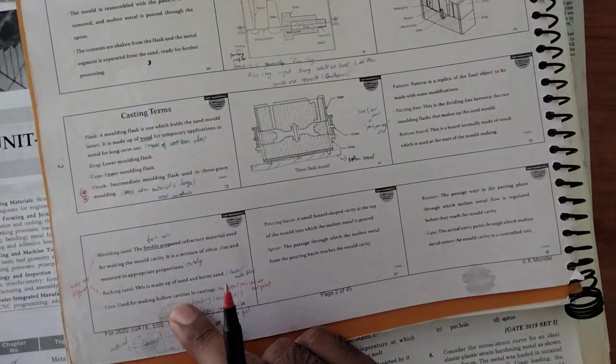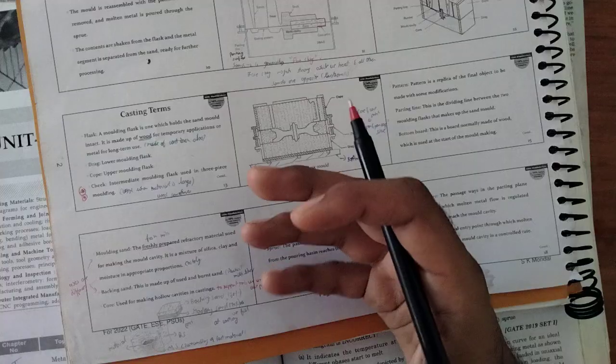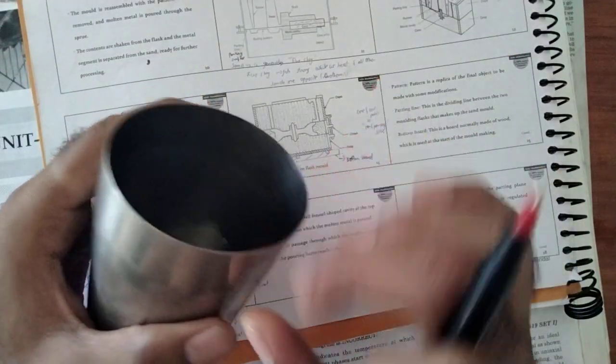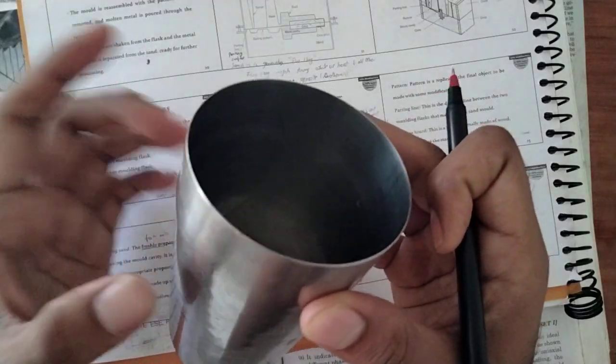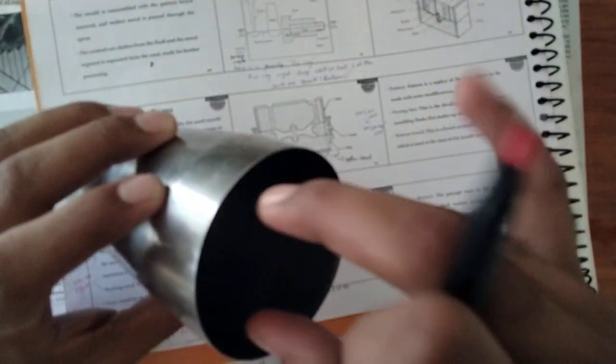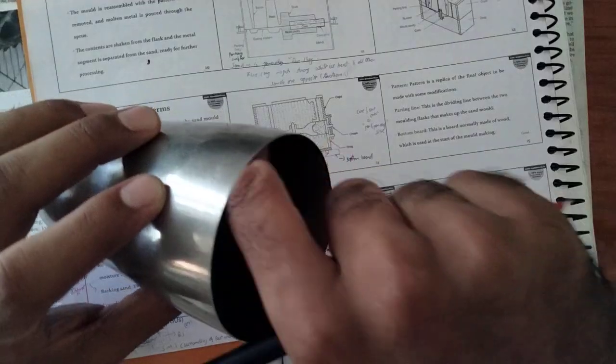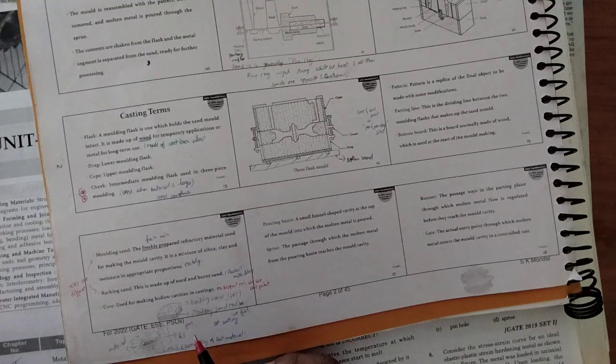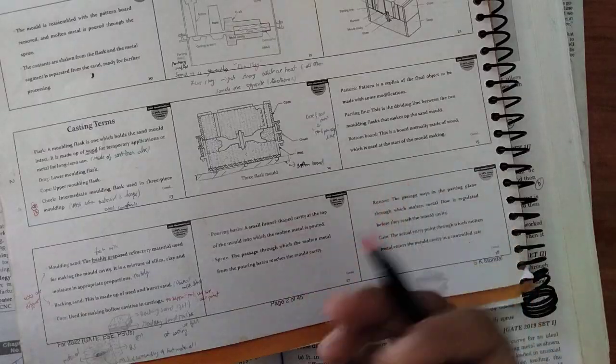And the core is used for hollow casting. Suppose you see a cylinder, just take this tumbler. For this tumbler you can see like this, this is sheet metal. It's not made by casting, but for general industry too, you can see how much portion is there. They will place something here and then do the casting. So the core is used for the hollow cavity. Mostly the freshly prepared molding sand will be used for 70 to 80%, and the backing sand will be used much less. You can see at this center portion the material is there. Okay, so next one is the pouring basin. I just told you the pouring basin means, you can see this one, this entire thing.